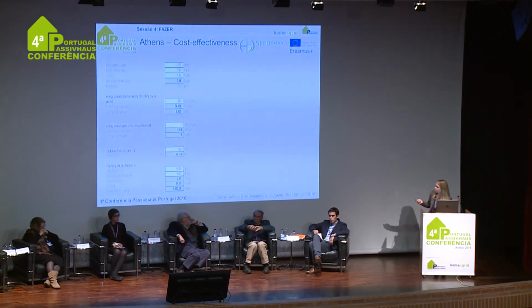And now coming to cost. In PHPP, I've mentioned this morning that there is a sheet where you can compare two variants according to cost. In this sheet, you can enter the energy price of your country and how much your investment cost. So this retrofit cost almost 50,000 euros in total, which is a normal cost for Greece for a retrofit, and represents 400 euros per square meter. And now you can see in red the annual cost for heating. In blue, the new annual cost since the building is retrofitted, and in green, the annual cost for heating taking the loan into account.